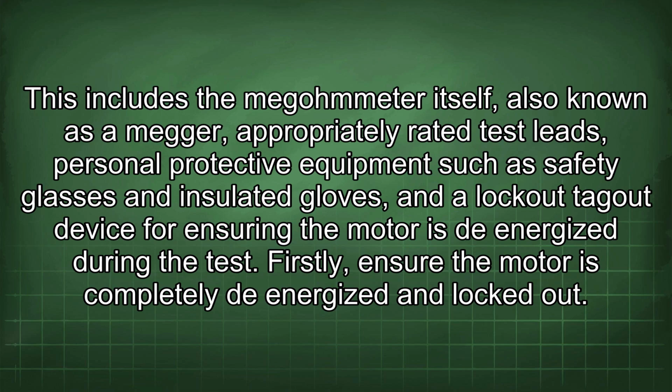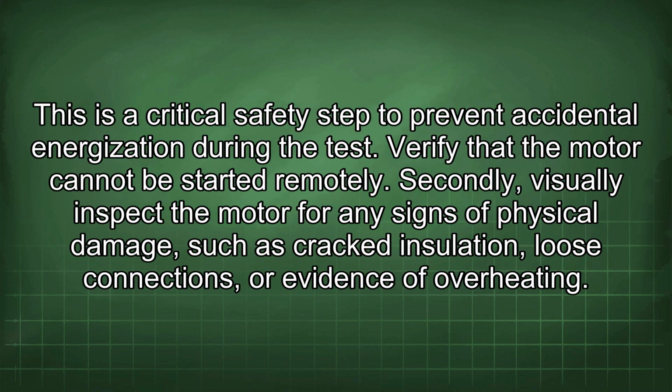Firstly, ensure the motor is completely de-energized and locked out. This is a critical safety step to prevent accidental energization during the test. Verify that the motor cannot be started remotely.